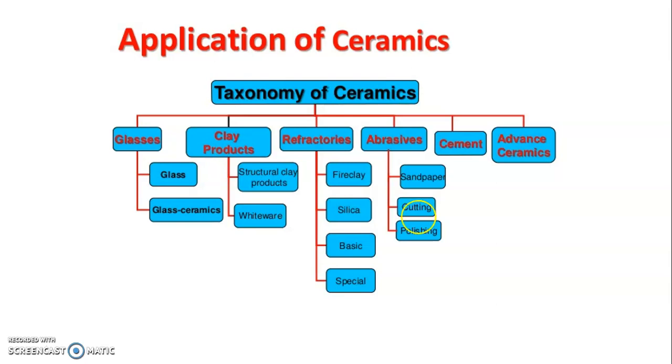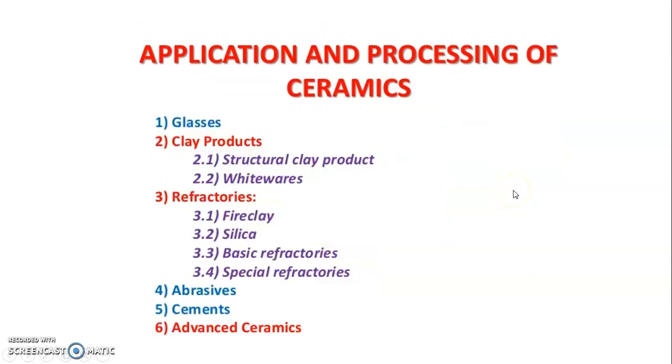Then the applications of ceramics are glazes, glass and ceramics. Clay products are structural clay product and whiteware. Then refractories are fire clay, silica, basic and special. Then abrasives are sandpapers, cutting and polishing. Then cement and advanced ceramics. So these are the applications of ceramics.